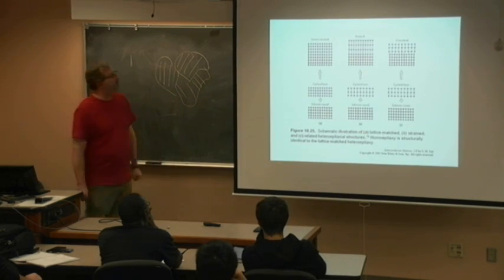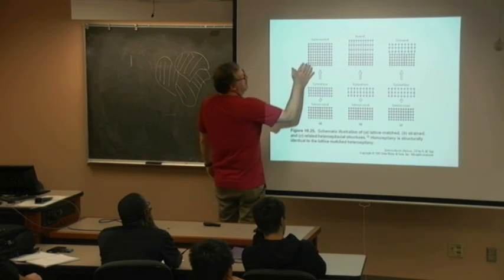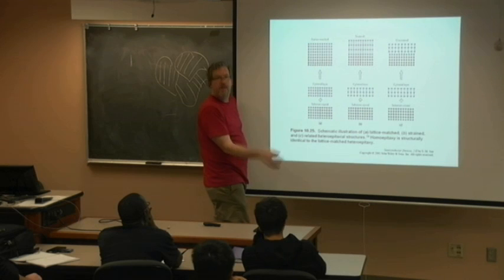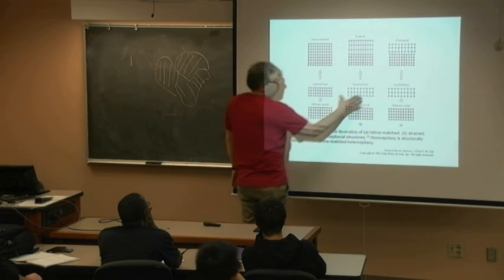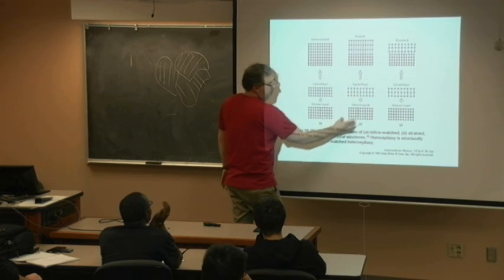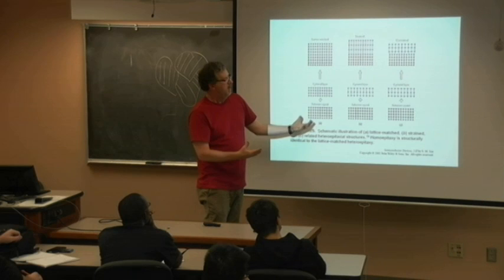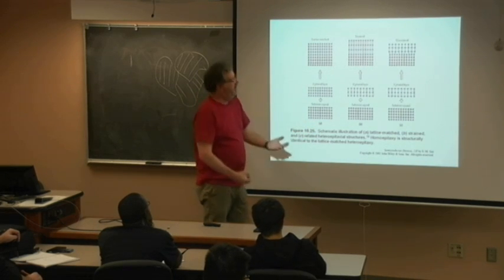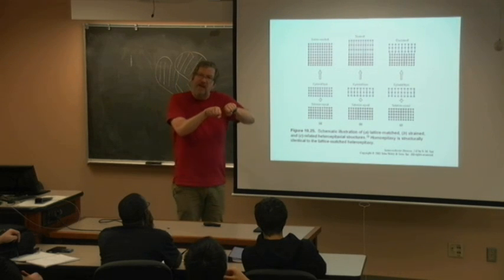And so this is the misfit dislocation. This is basically the Jenga tower. If I grow silicon on silicon, everything's happy. It's all registered. If I have larger blocks on smaller ones, so it's Tetris, but they don't fit, but I somehow force it, then they're going to distort. And when I distort, those bonds are bending.